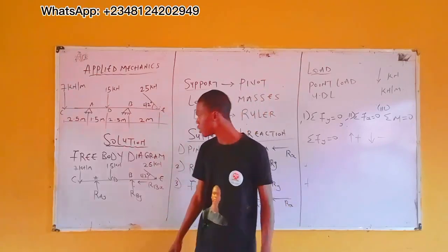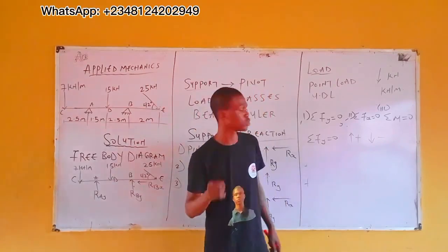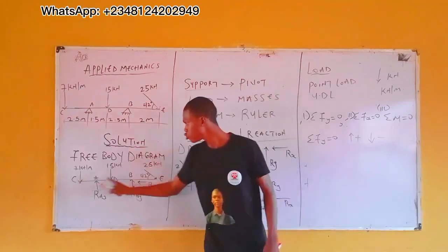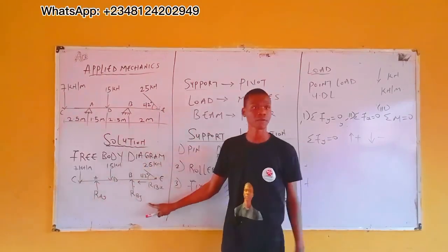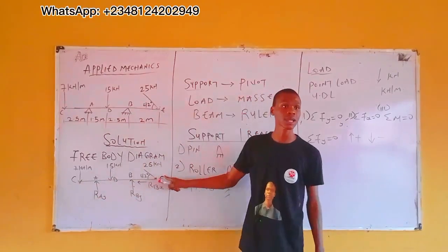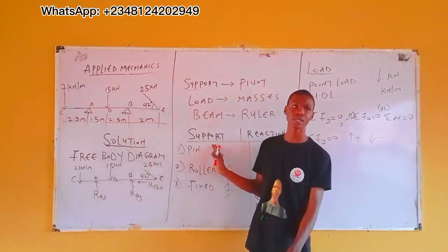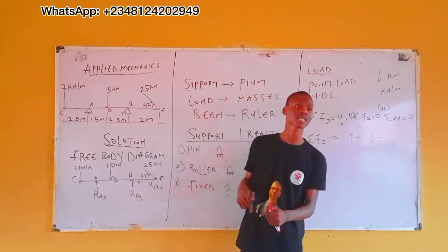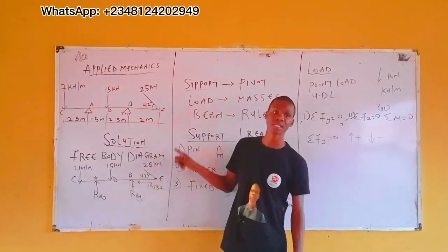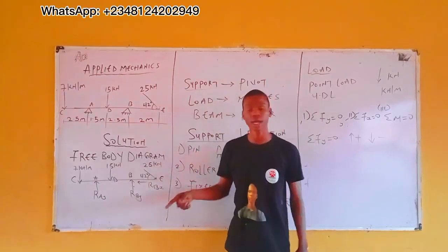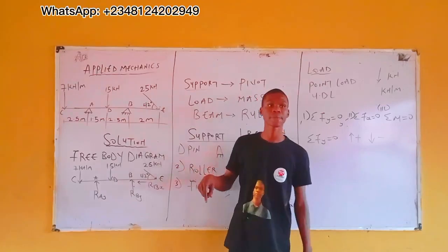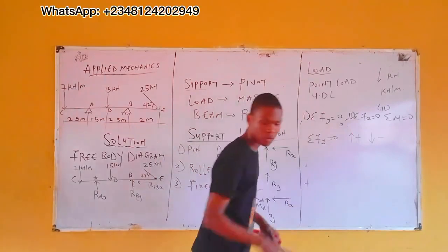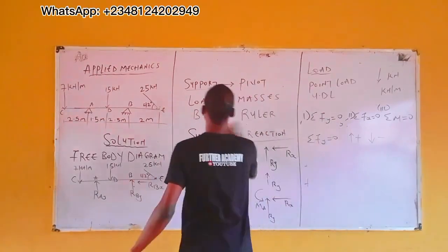You have 6. How many vertical forces do you have? How many forces of this nature do you have? We have 5: 1, 2, 3, 4, 5. You know, this is an inclined force. This inclined force, you can resolve it to the vertical axis, and also to the horizontal axis. When you are considering vertical, you need this inclined force in vertical. When you are considering horizontal, you need this inclined force in horizontal. Meaning, before considering this condition, let's resolve our inclined force.